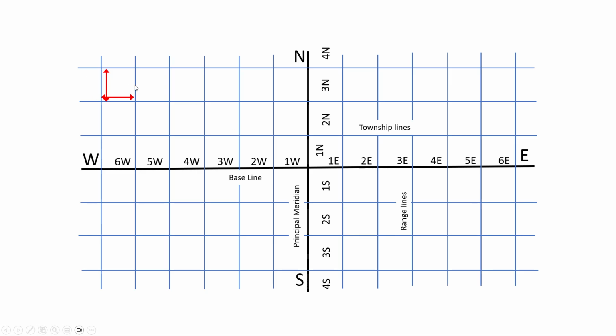So let's just take a section here, and we look at that, and it's a township. A township is 36 square miles. So that's what this is, a township. Okay, and if we look at the block where we're at here, we're looking at township 3 north. So we go to the baseline, and we count blocks up. So 1, 2, 3. That's how we get 3 north.